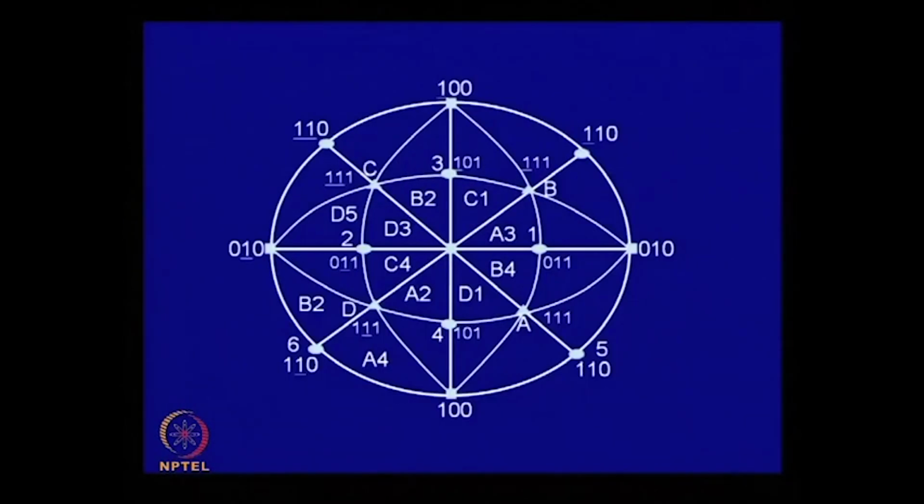And this is shown over here in this standard 0 0 1 projection. Now, in this projection, all the poles of type cube, 1 0 0, they are shown, and 1 1 0. So, these are the crystal axes 1 0 0, 0 1 0 and 0 0 1.